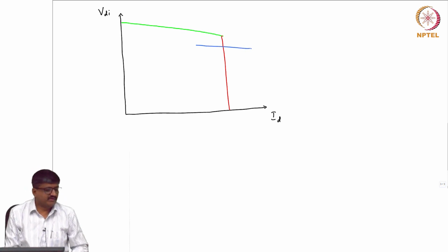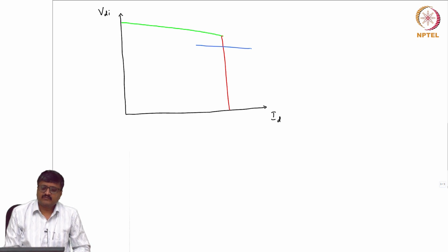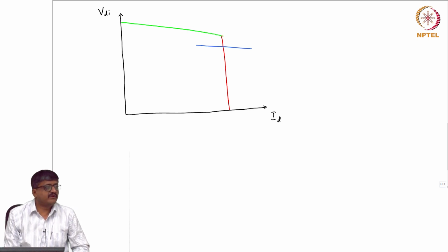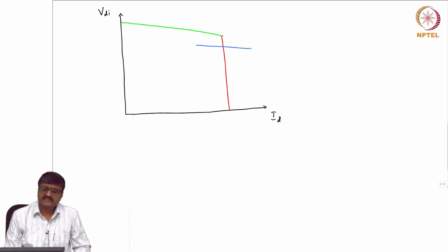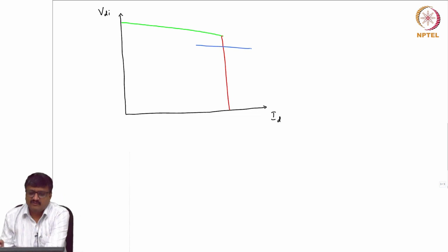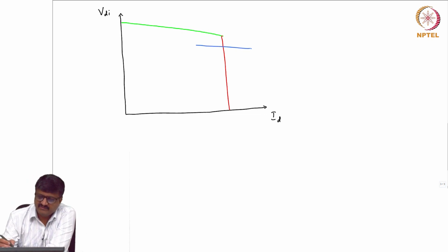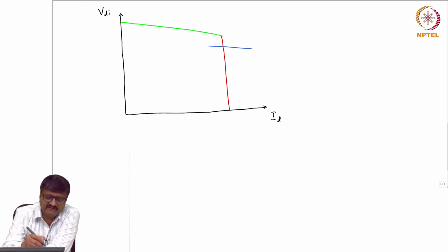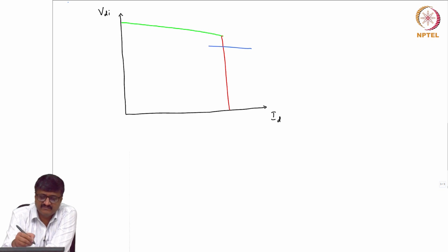So, I have shown one red line, constant current control at the rectifier; one green line, minimum alpha R, that is also at the rectifier; then CEA control. CEA control is the blue line for the inverter. Now, what we normally do is, if the situation of rundown can occur, then to avoid that we provide a constant current control even at the inverter.